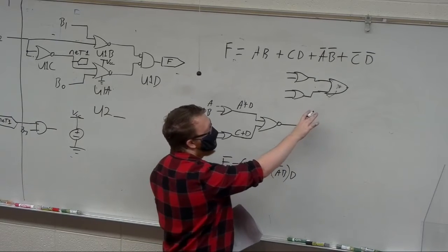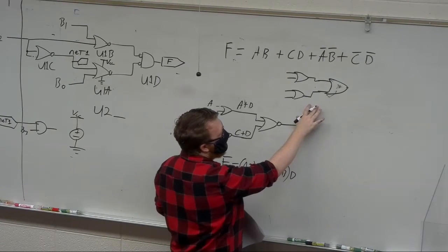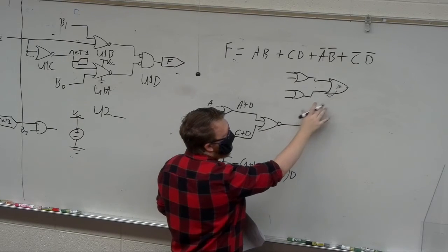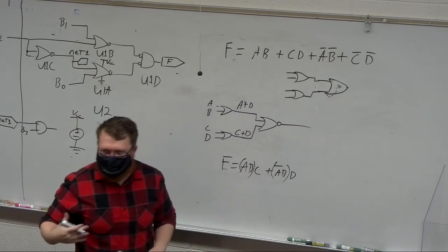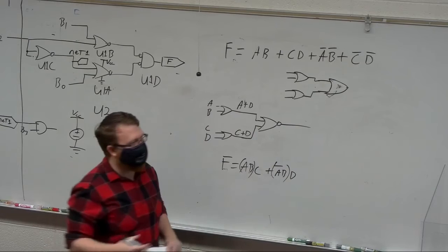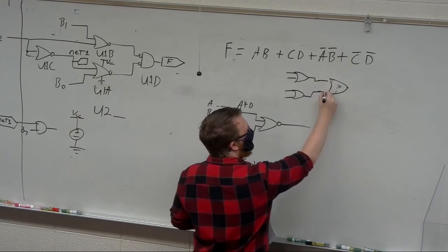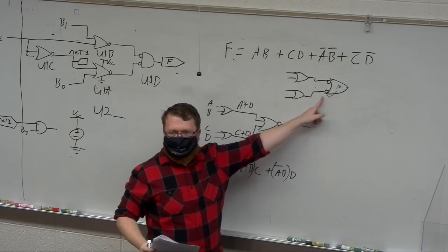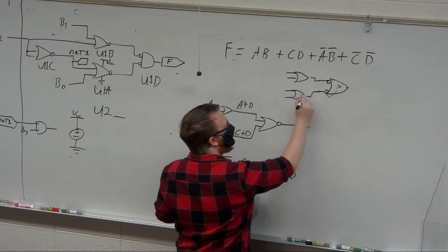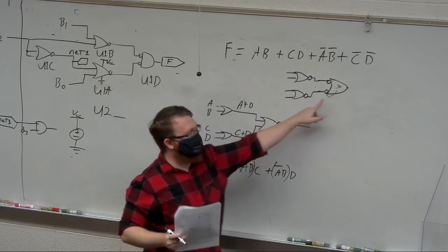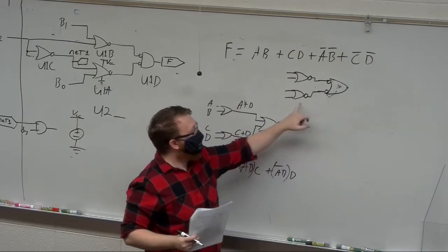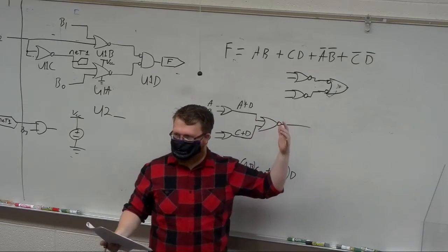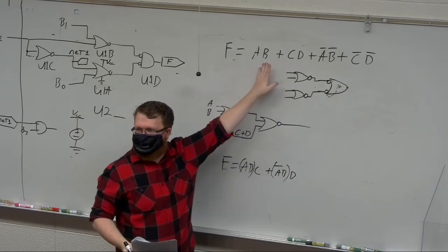And if you recall, you can have a situation where your logic expression, if you start with an OR gate, it's very easy to go into NAND gates, right? Because all I have to do is invert this input, invert that. Now we're a NAND. But I've inverted things, so now I have to move some bubbles. So now I'm going to invert and then de-invert. So this is the same expression, but now we have NANDs and NORs. We're good, right? Everybody's happy. And then we can continue on building these.